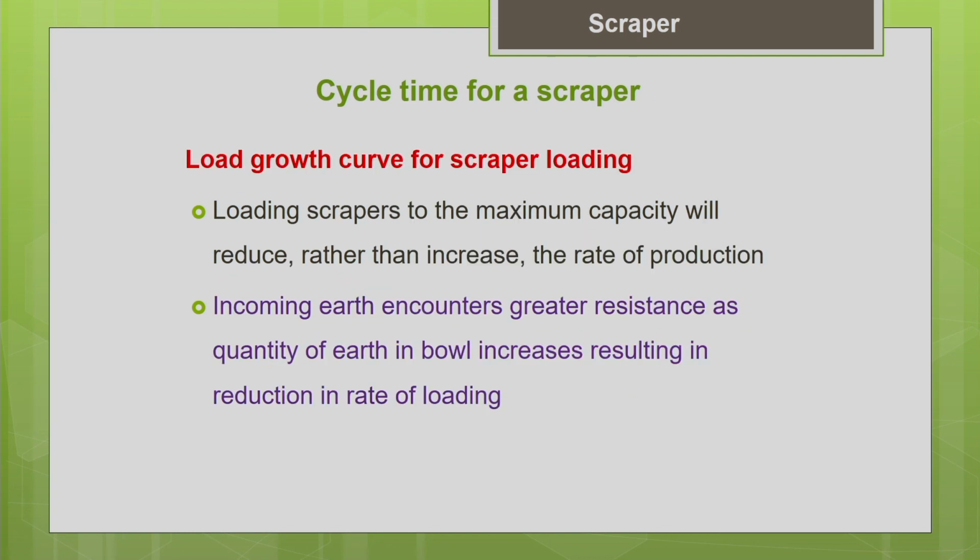Another important concept which we need to know is the load growth curve for scraper loading. We commonly believe that when we fill the bowl of the scraper to the maximum capacity, we are going to maximize the production. This is a common belief, a common assumption, but that is not true. People have done studies and proved that when you try to load the scraper to its fullest capacity, the production starts reducing beyond a particular time.